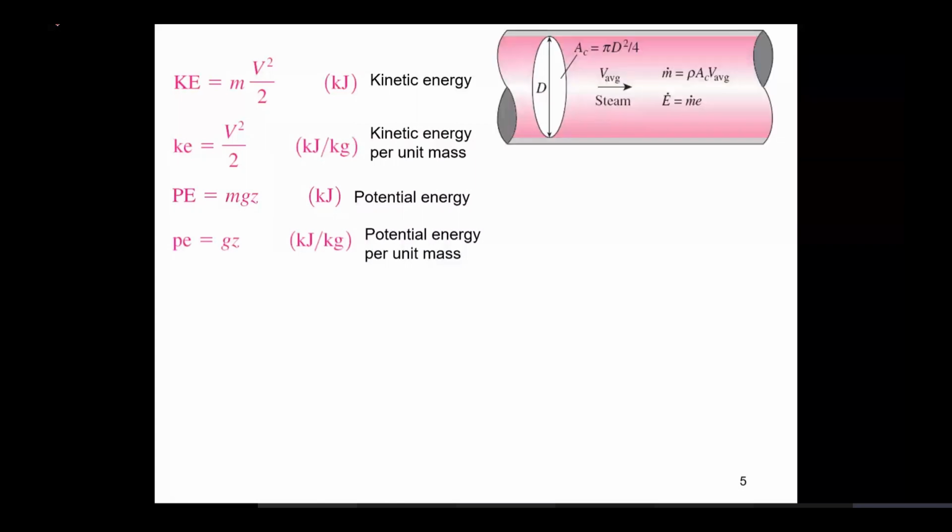Normally, when you are dealing with an open system, you express the fluid flowing through the system in terms of mass flow rate. When you have a dot on top of a dimension, in thermodynamics that means you're referring to that dimension with respect to time. Having a dot on top of mass means mass flow rate, which is nothing but kg per second. Clear? You can also express mass flow rate in terms of density multiplied by the volume flow rate.